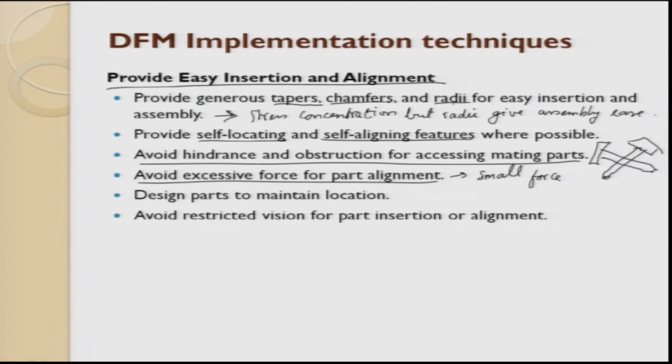Generally, for example, take the dispensable water bottle cap. You lock it and unlock it, and it has a multi-thread start. With the polymer, with minimum effort you break the seal. If you apply excessive force, the part may get misaligned or the bottle gets squeezed and other things.